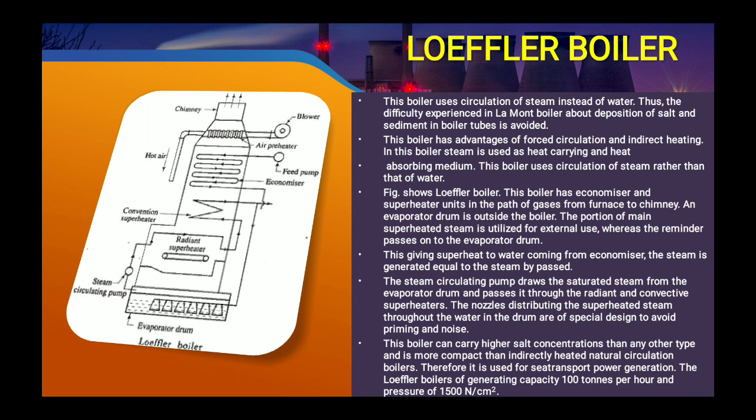And this boiler can carry higher salt concentration than any other type, and is more compact than indirect heating natural circulation boilers. Therefore, it is used for transport power generation. The Loeffler boiler has a generating capacity of 100 tons per hour and a pressure of 1500 Newton per centimeter square.